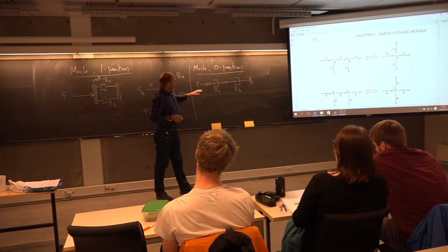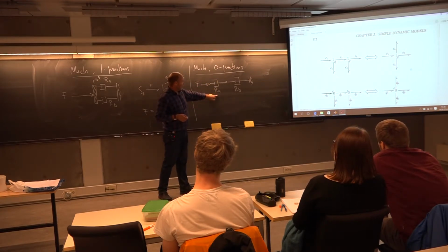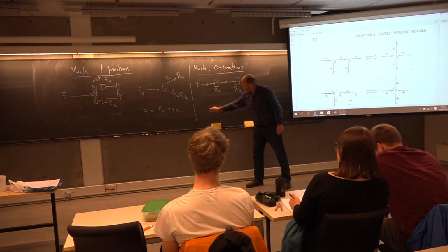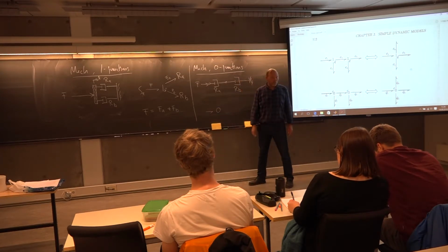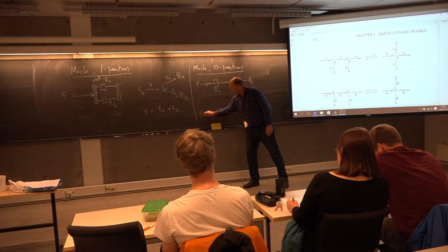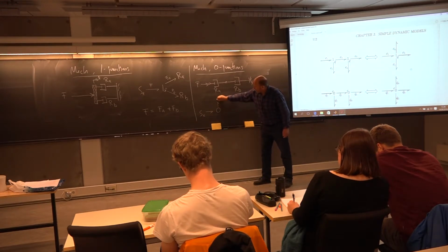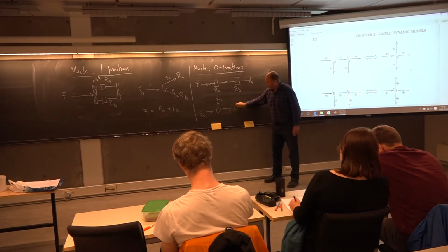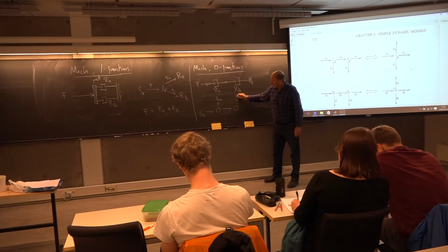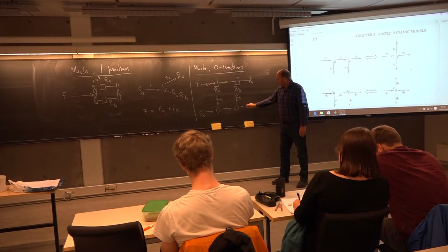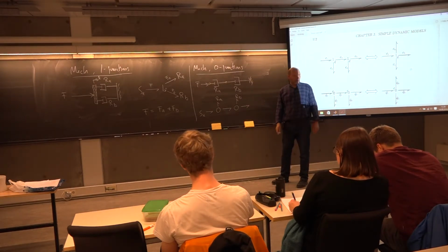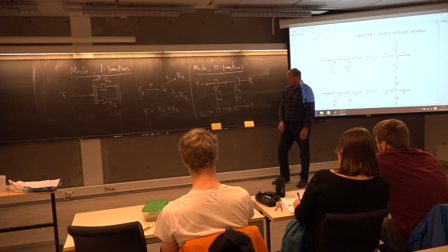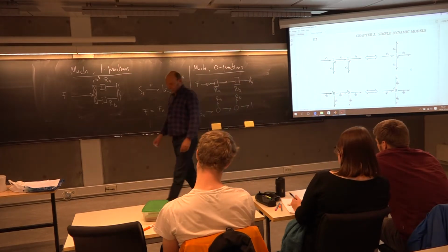So for such a damper, to include it in a bond graph, here you will use a zero element. So you will have one force hitting it from the left. That's the effort source. And then we hook up this element. And then we continue with another zero junction, and then we'll have the next damper, and then finally you have a solid wall. What's a solid wall? Well, that's something that has its own unique velocity. So there typically you will use a one junction to describe a solid wall.